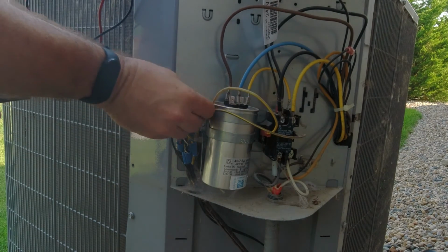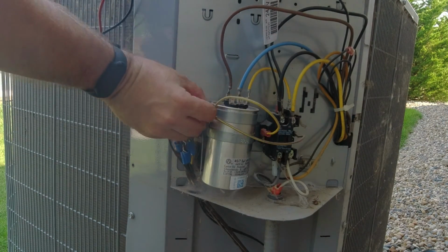Usually I have a 10-in-1 screwdriver, but I can't find it right now, so we're just going to use a socket driver to take this off. One other item I want to point out is you should also check the voltage on the 24-volt side. There's less of a risk of it giving you any type of injury, but it's always a good idea to check those things. So again, putting your multimeter in voltage mode, just check to make sure there's no voltage on the 24-volt connector as it comes in to the contactor.